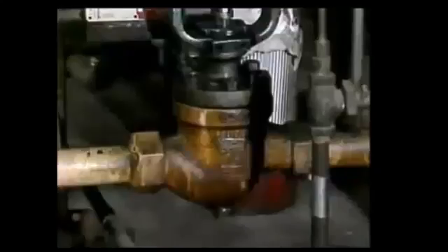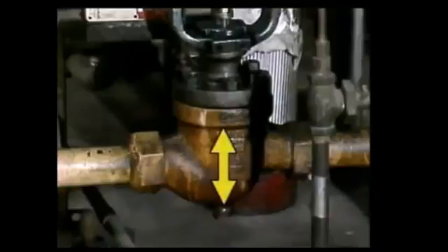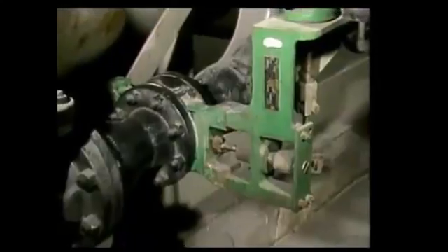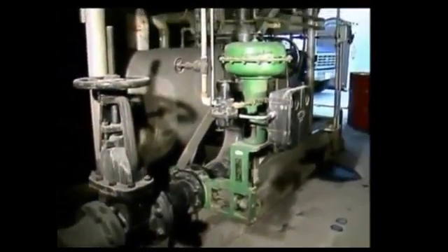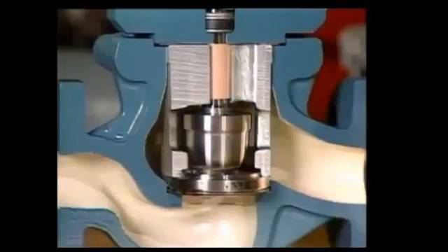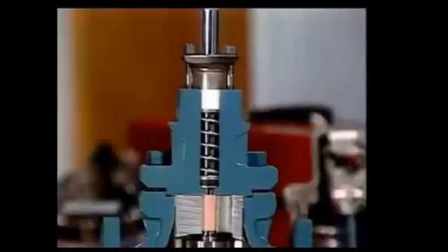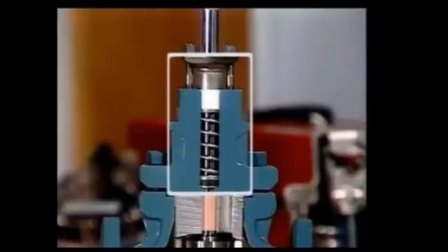Control valves can be either linear, that is, the stem moves the valve disc up and down, as in globe valves, or they can be rotary, which means that they're positioned by rotation. Butterfly valves, which open or close with a 90-degree turn, are examples of rotary control valves. This is a globe-type control valve. It has the same basic parts as a manually operated valve, including a valve body, a disc, a seat, a bonnet, a stem, and a packing assembly.